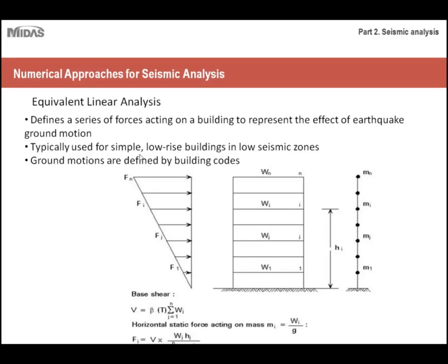typically for smaller scale projects in low seismic zones. It's also defined by your building code. Depending on the region you're in, the code will be enforced, and you can just follow a step-by-step procedure on how to model your seismic loading. But essentially, what you're doing is assuming that the seismic loading follows a distributed loading pattern.